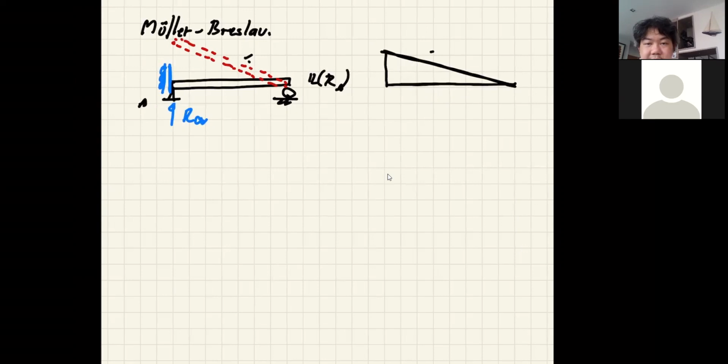Once you figure out the shape, you can figure out the magnitude of your influence line as well, since the influence line is constructed by putting the unit force on the structure. So for the influence line of RA, the reaction at A should be equal to 1, the unit load itself, when the load is on top of A. That becomes the shape of the influence line.